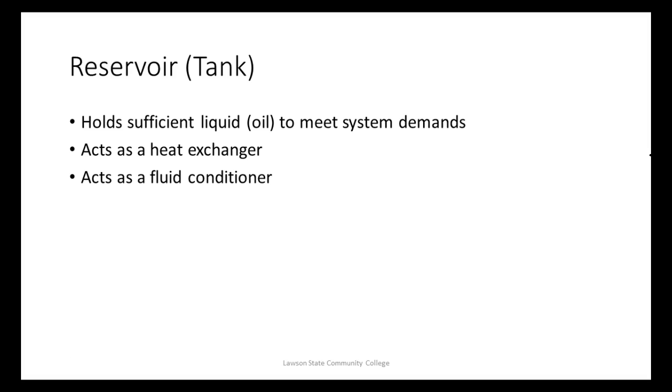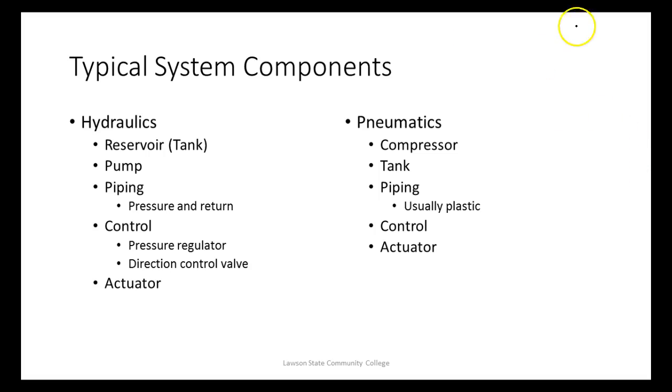And we got two problems. Not only do we get moisture from compressing it, but once we get it into the tank and it starts chilling down, what's it going to do? It's going to release moisture too, right? You understand? So that means on this pneumatic system, we need to make sure we come up with some system where we manually go out and drain that compressor, not the compressor, the tank, constantly, right?